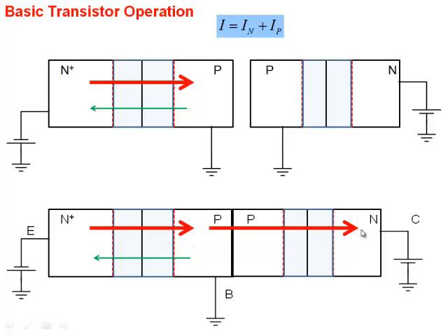So what is the collector current then? Collector current will be equal to 99 electrons. Emitter current will be equal to how many carriers? 101. And base current will be equal to, one hole goes here, and one electron was recombining with a hole, so another hole has to come and replenish the hole that recombined. So the base current would be equivalent to 2 holes, right?